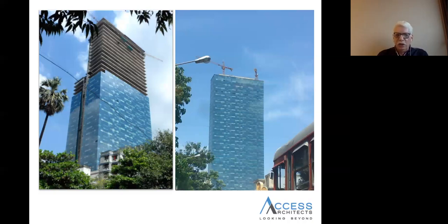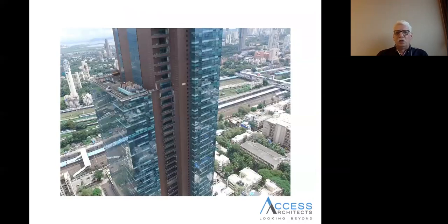So the basic criteria was that you hang the glass facade from the top. It is only connected to the lower unit, which is also fastened. The lower unit is fastened to the slab. And that would allow that movement to happen, which most of the time people think that the glass facade is fastened at every slab, which is incorrect. So this is how the building presently looks.